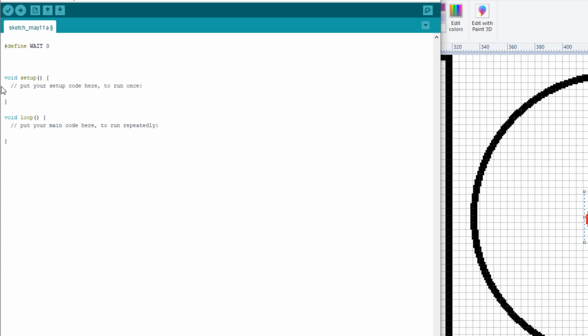But just keep in mind that the way that we do some of these is going to determine where those values are kept. It is important that we don't put everything in using #define, simply because we can run out of memory and we can corrupt things, especially if you're using a board with less memory. So we're going to use it for very specific things, and then we're going to use constants as global variables.